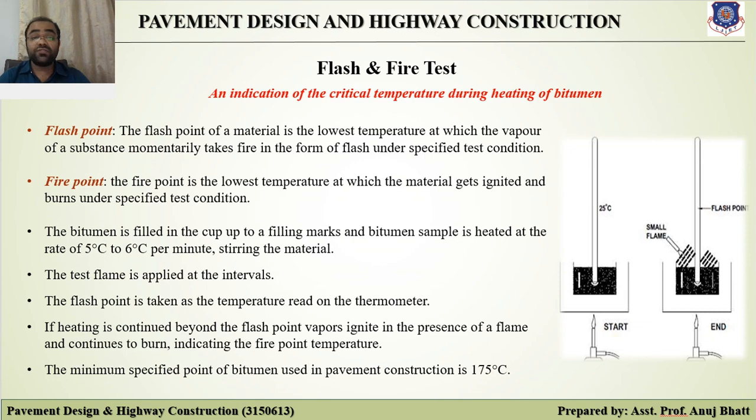This condition is very hazardous and it is therefore essential to quantify this temperature for each bituminous grade so that paving engineers may restrict the mixing and application temperatures. As mentioned above, this test gives an indication of the critical temperature at and above which suitable precaution should be taken to eliminate fire hazards during the heating of bitumen.